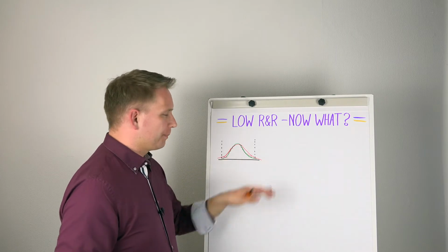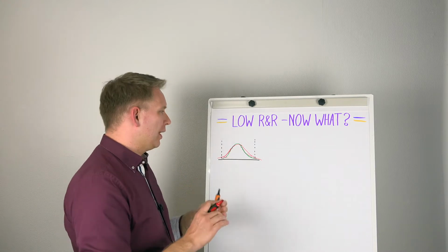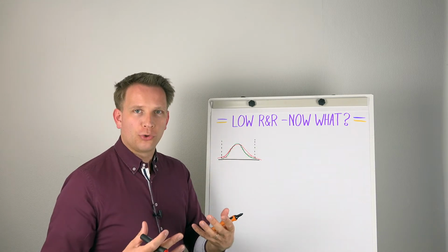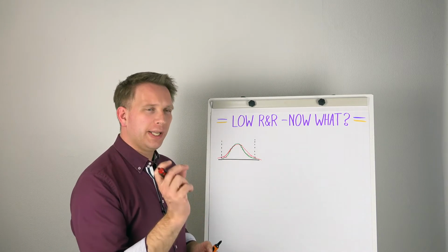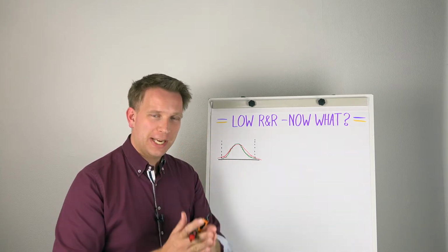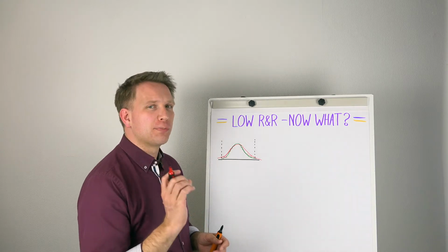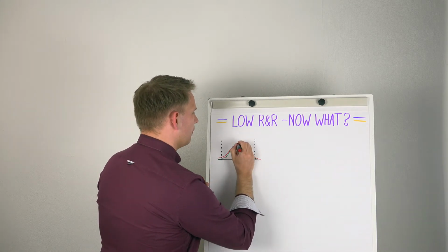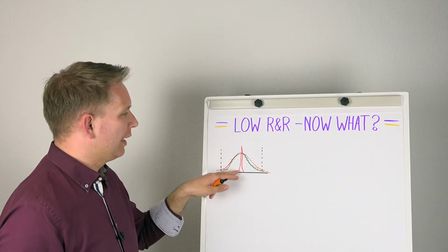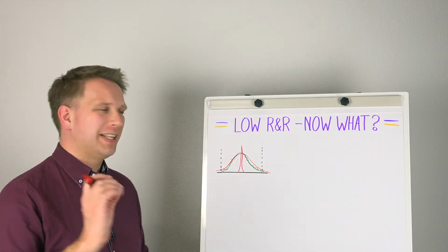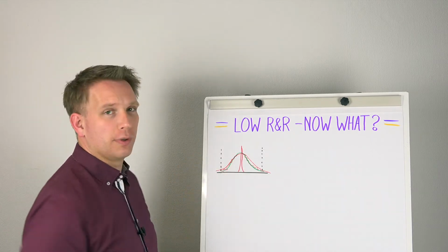Now, this way is pretty difficult to judge. What does the Gauge R&R do? It sort of eliminates the whole green part, and it tries to back calculate only if you would have exactly the same part, what your measurement system would be doing. And you hope that that is a very small distribution. In fact, what you want is that this distribution is less than 10% of the green one and also less than 10% of your spec range.